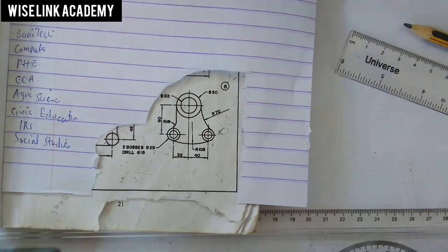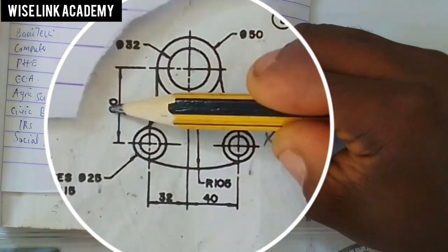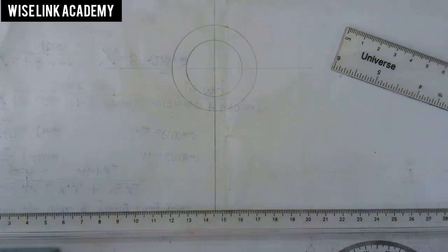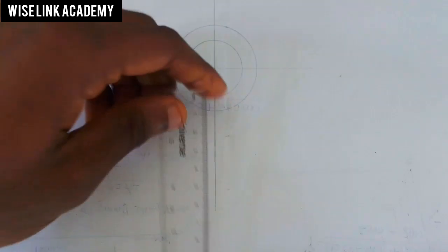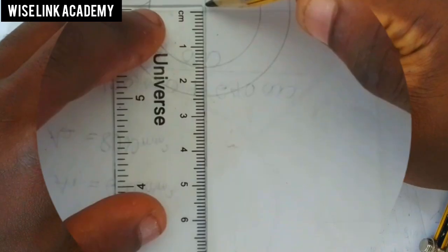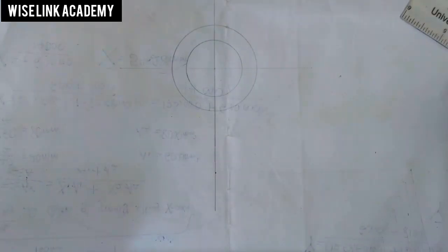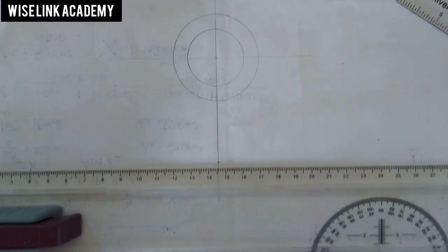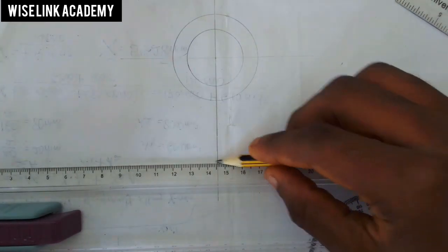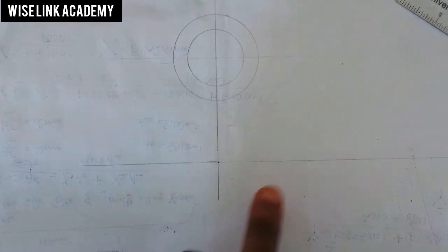Now what do you observe? They said from this point here to somewhere down here is 60. So let's measure 60 downward. That's the reason why I extended this line earlier to locate that 60. So I'll measure 60 from this point here to this point, my point 60, right? So therefore I will take my t-square this way. I will draw a vertical line this way. So this vertical line I have drawn this way.